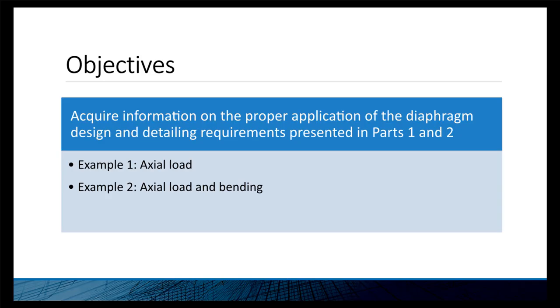Okay, so for other cases where you have a fixed head, you consider that pile cap just like a continuous beam. You can calculate what the moments are and then transfer those moments down into the piles. That would give you a distribution then, depending on the soil, the depth of the pile, what the actual maximum bending moment would be in the pile. And there's a number of software out there that would do that for you.